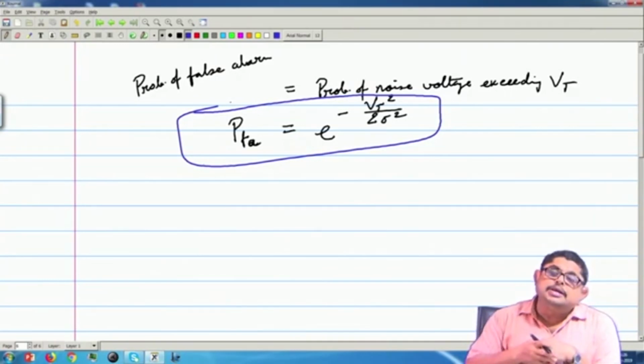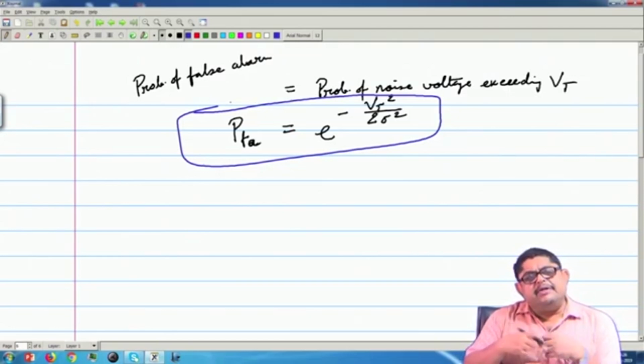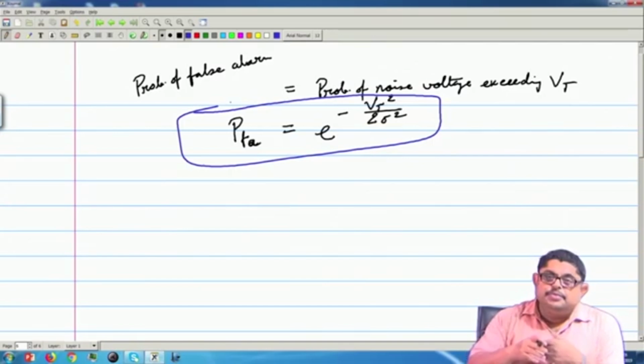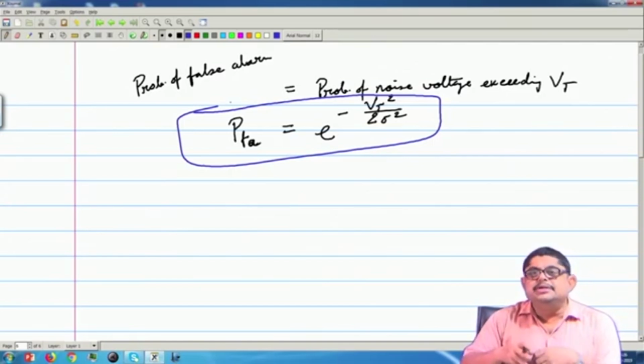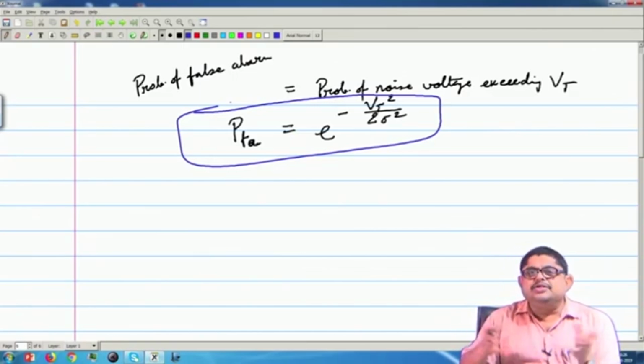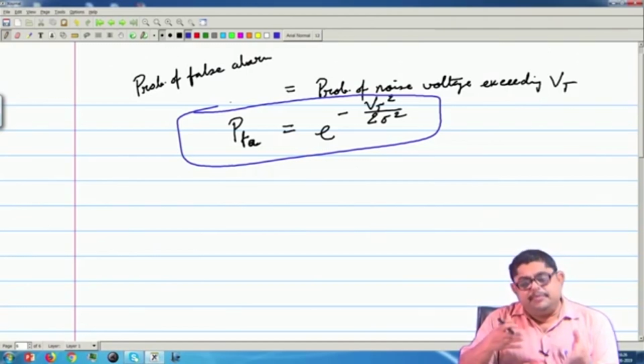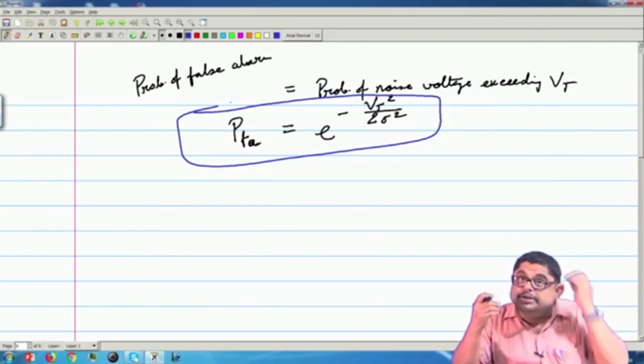More meaningfully, can I not say it in terms of time, that on an average every 20 seconds a false alarm comes. That is why, instead of working with probability, because probability is meaningful to the educated person, but radar gets operated by many persons who are not so highly educated. For them, the more important thing is how often the system raises a false alarm.